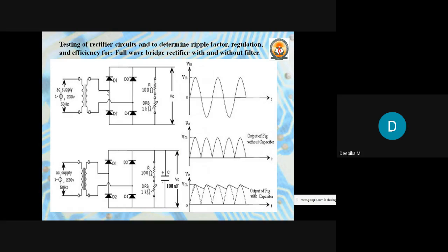First we will build this diode circuit in this manner, that is cathode to cathode, like this on the breadboard, and across it we are going to connect the 100 ohm resistor, that is the power resistor, and also the DRB box, and the output will be measured over here. One end of the transformer is connected to this leg, and the other end of the transformer is connected to this leg or this arm. Okay, so like this the connections are made.